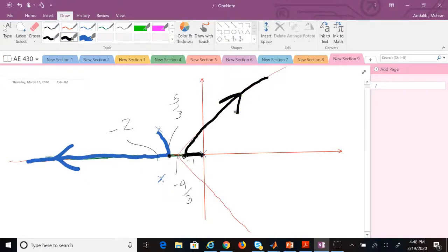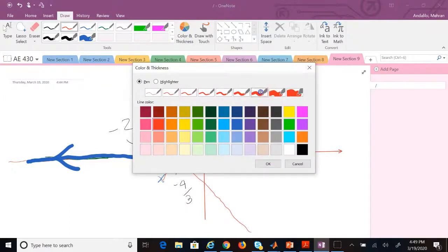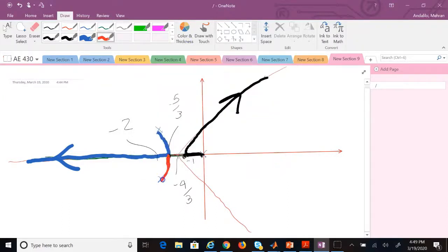And then the final one comes from what? It comes from this one at positive 63 degrees and then goes to this other asymptote, right? So it goes like this, to this breakaway point, and then ultimately falls on this asymptote. So there are 3 branches of the root locus, and this point is square root 5 and this point is negative square root 5.